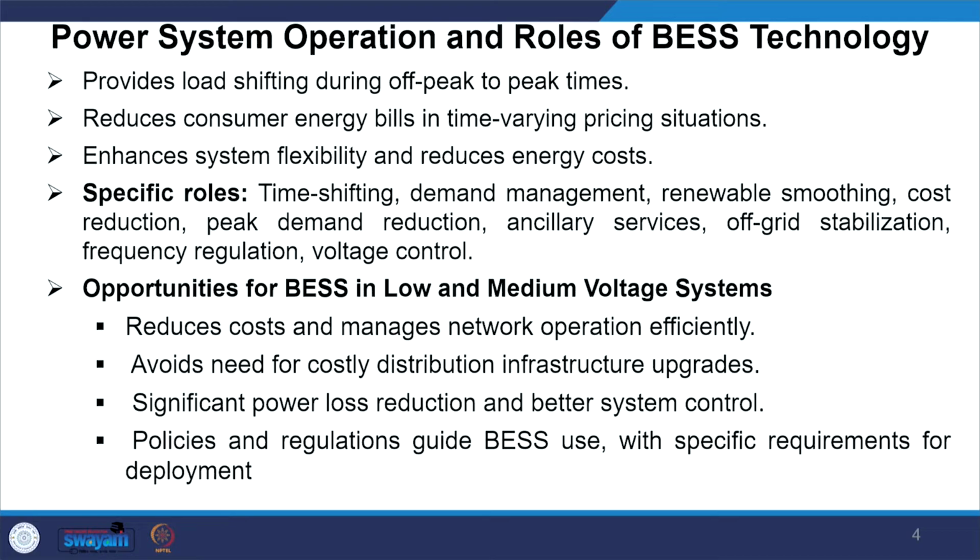Hence, today, lithium ion batteries are quite popular in renewable integrated distribution systems. Now, why do we go for storage? The main reason is to provide load shifting from off-peak to peak times, because during off-peak hours the storage can store the energy and discharge during peak hours, which also reduces the consumer energy bill in time varying pricing situations, because during peak hours the cost of energy is very, very high.